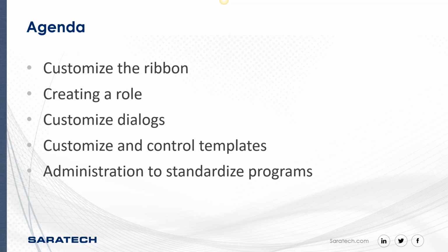So what I'm going to do is show you how to create a custom environment that controls all of your templates, all of your settings, all of your roles, all of your dialogues, and it's going to be on a separate location. Then we're going to point our environment variable to that new environment instead of the out-of-the-box environment. And what this does for you is it gives you the ability to back up at any time.